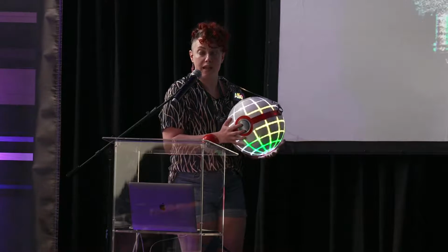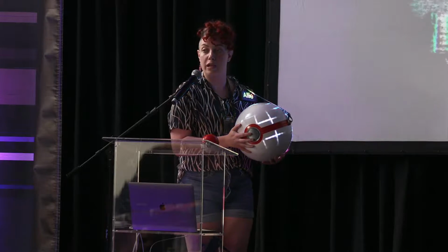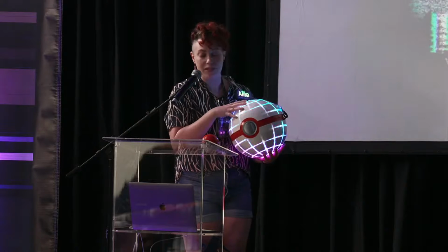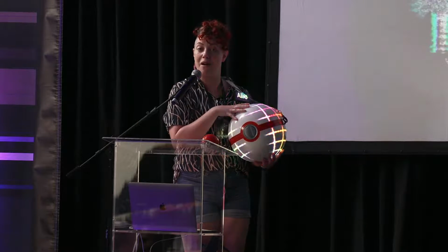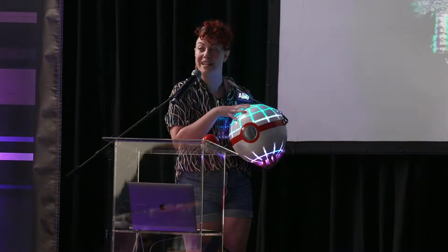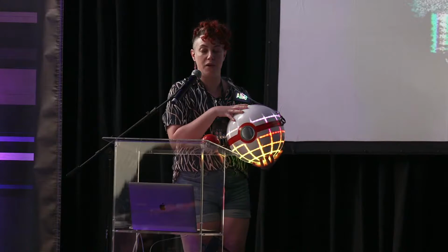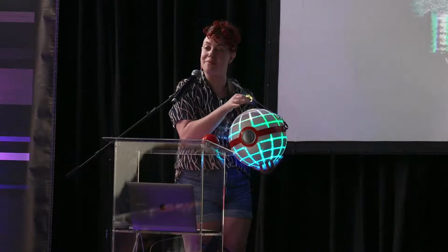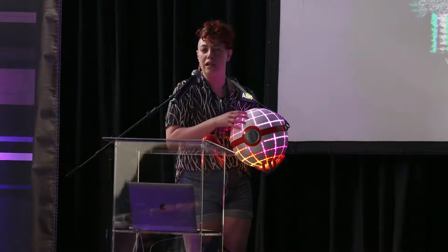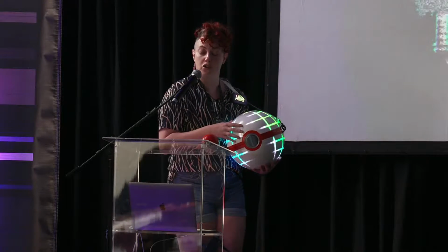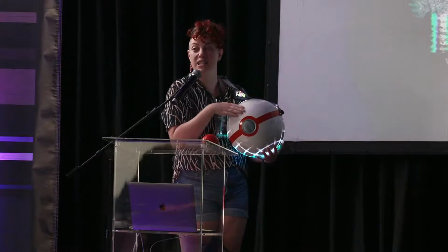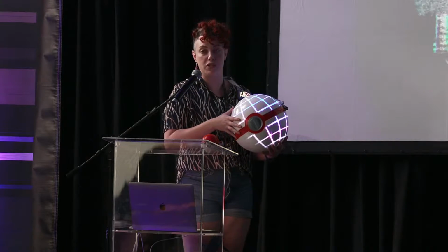With that being said, because I imagine there's a few 3D printing nerds out there in the audience, most of the prints, the large prints, were all done on a heavily modified CR10S Pro V2, which has a Hemera direct drive extruder and a Volcano hot end printed with a 0.6 millimeter nozzle. So a little bit faster. I could have gone with a larger nozzle, but then I wouldn't have gotten this small layer height. So again, I wanted smooth. So we went with a 0.2 millimeter layer.